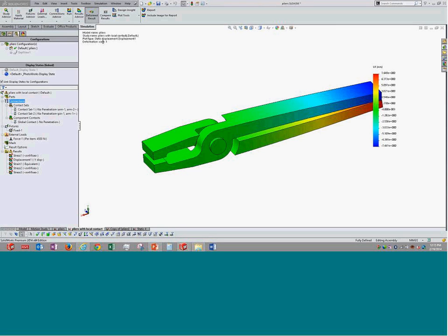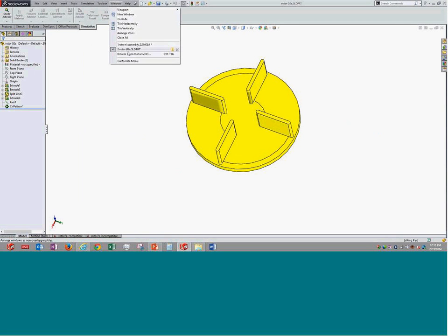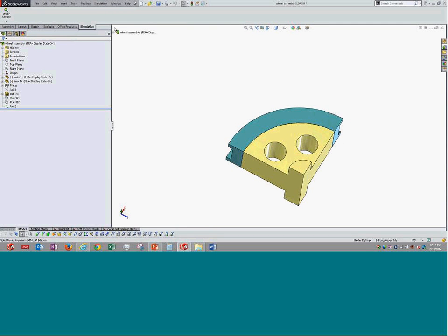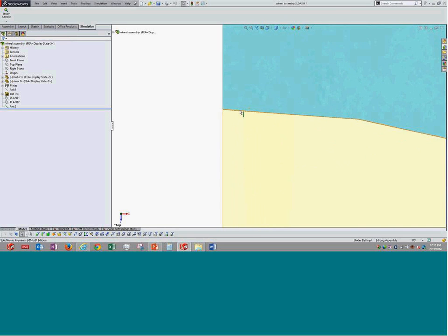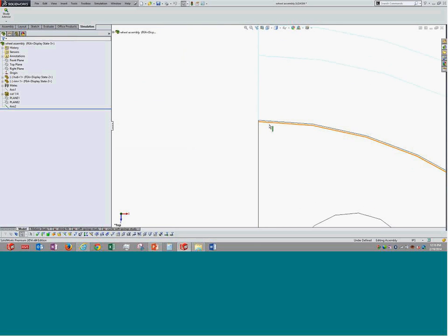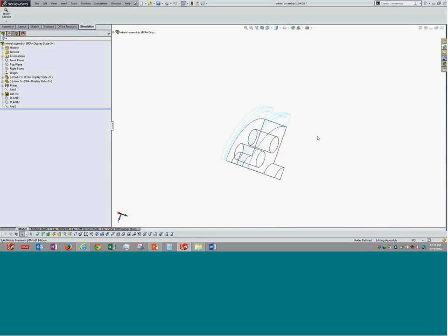There is a set for the shrink fit. Must the parts be overlapping each other? Answer: yes. Let me go into this example, that is better. Let me check where it is. Okay, now a regular example. This one I'm about to use for the shrink fit simulation. In this image there is a kind of interference present, and that is what is going to help the software set the shrink fit.